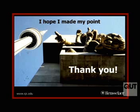There's a building in Hobart. When I was at the University of Tasmania, the harbour office at Hobart had 4 vertical axis turbines on the roof. One of them decided to shed some of its blades one day, and that in the middle of the city wasn't such a good idea. The air is far too turbulent around a tall building. Tall buildings, unless they're airport control towers, are buried in typical roughness. They stick well above in some locations, but they're buried in roughness.